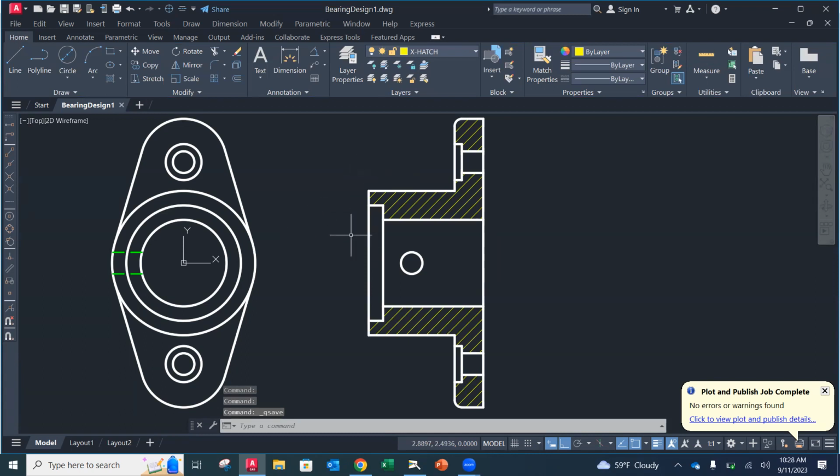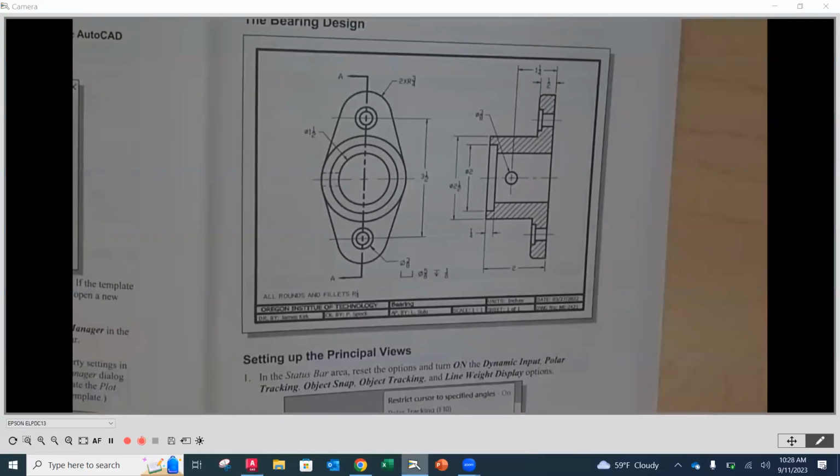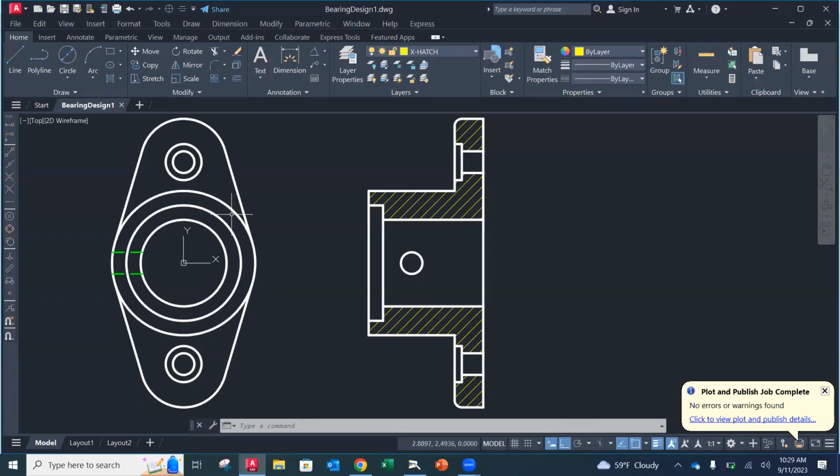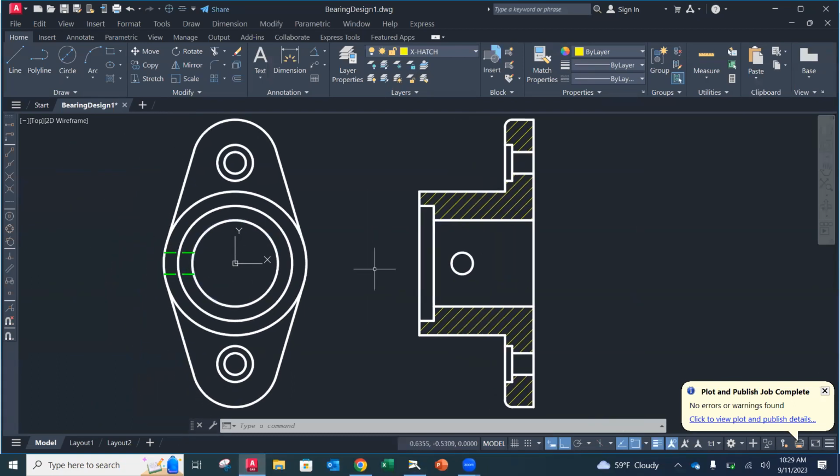No. Okay. So now I'm ready to put in what? What am I left with here? I have center lines, and what else? The cutting plane line. Yep, the cutting plane line and the center line. We're going to put the cutting plane line in first. The reason we're going to put it in first is because it takes precedence over center lines, and my center lines would all have vertical components to them, wouldn't they? So I can't overlap center lines with my cutting plane line.